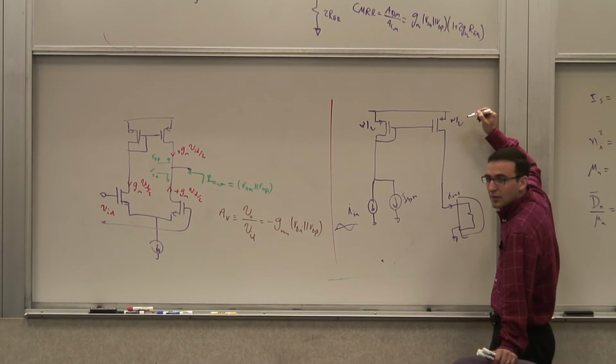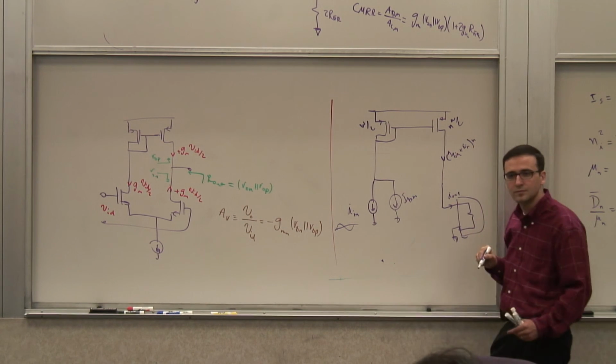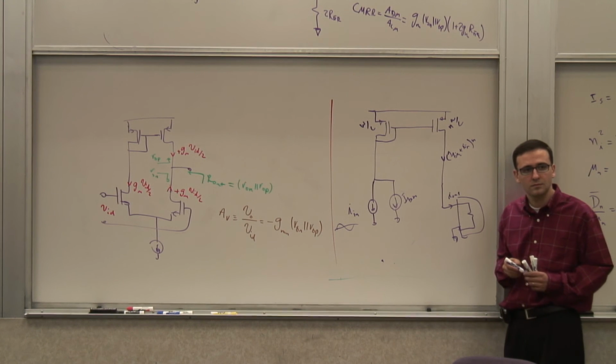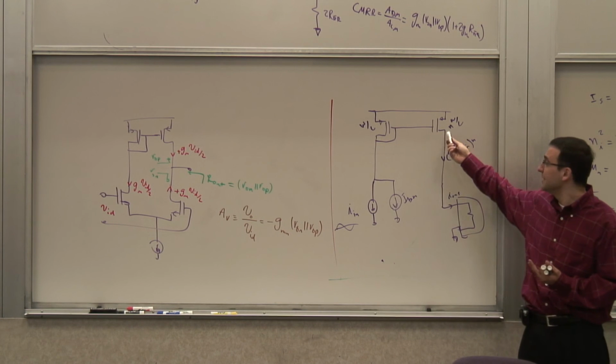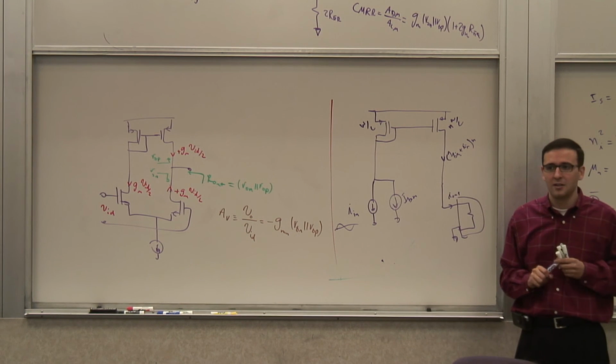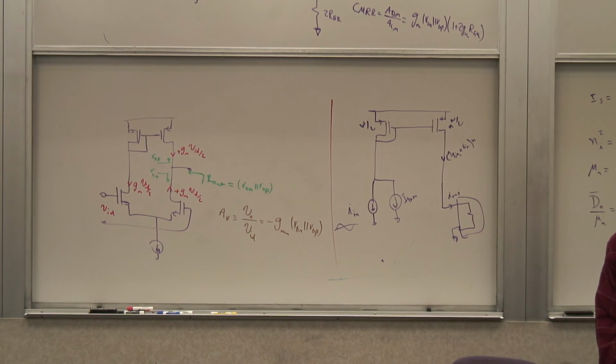Now, how can I make it an amplifier? You can change the W over L. Right, exactly. You make it n times larger, and then you copy that current down here. So this becomes I bias plus I in times n. Okay. Does it sound like there's any limit to this? This sounds like a free lunch. Say again? Not at the moment. Not at the moment. That's a good answer.